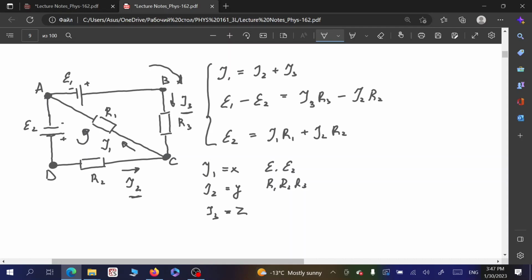So let us summarize this section. We introduced DC electric circuits. DC stands for direct current, meaning that the direction of current doesn't change over time. Its magnitude may change, but direction doesn't. And in the scope of DC circuits, we introduced batteries with electromotive force, the internal voltage, and internal resistance, which highlights the fact that batteries are not ideal and there is some voltage drop over the internal resistance.